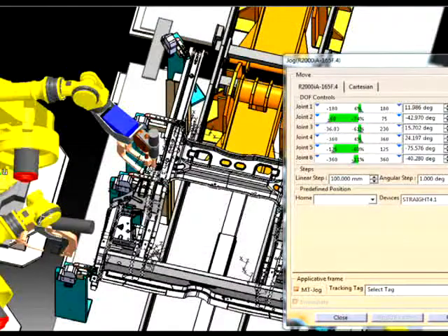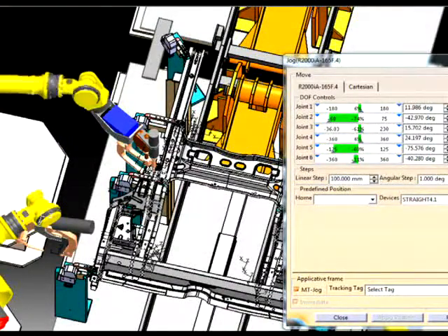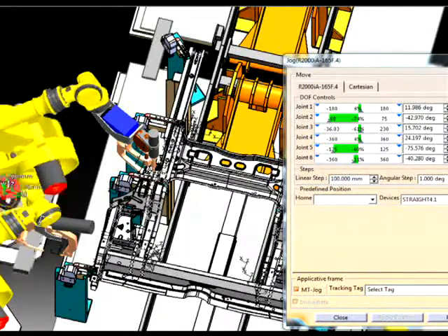Auto body assembly line processes are fluid and they change from day to day. Some changes can be minor, like adding a weld spot to a robot. Other changes can be significant and they can affect every robot in the work cell. For example, what if a robot needs to be moved forward or up? You would want to see how this would affect any given weld.